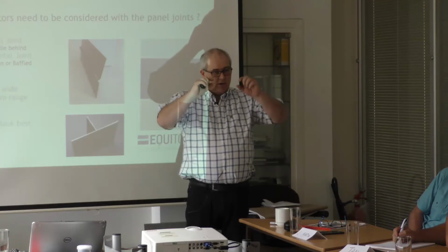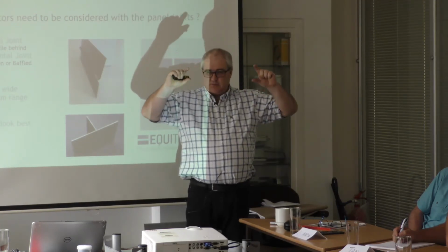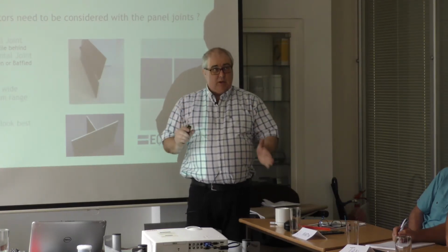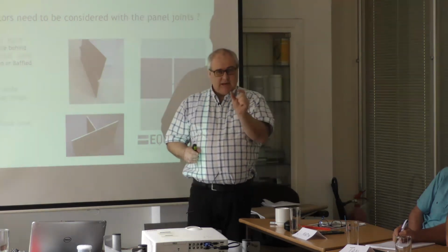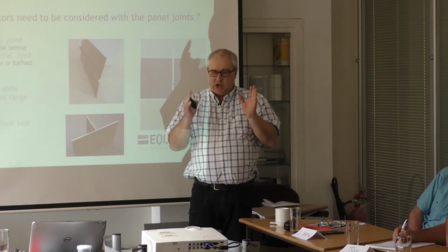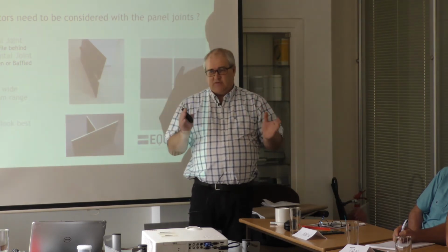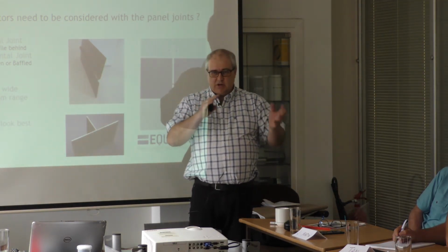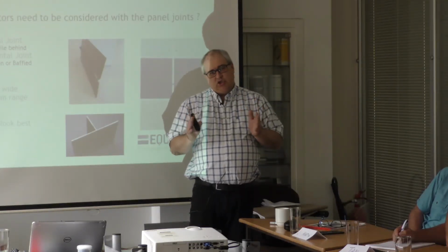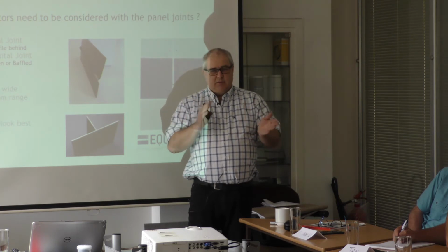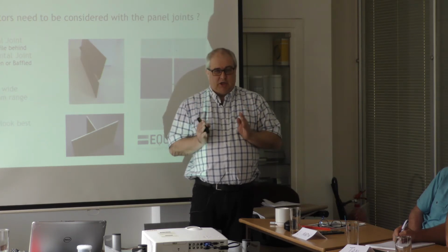Because your eye, there's a bigger percentage difference between the two. The same way when you're looking up the joints, which is what catches our eye first, that 10 millimeters makes it a little bit more tolerance built into the system for you guys when you're fixing it. That if you're a millimeter and a half out, it's a lot less noticeable and will cause you a lot less problems than if you're a millimeter and a half out on an 8 millimeter joint.